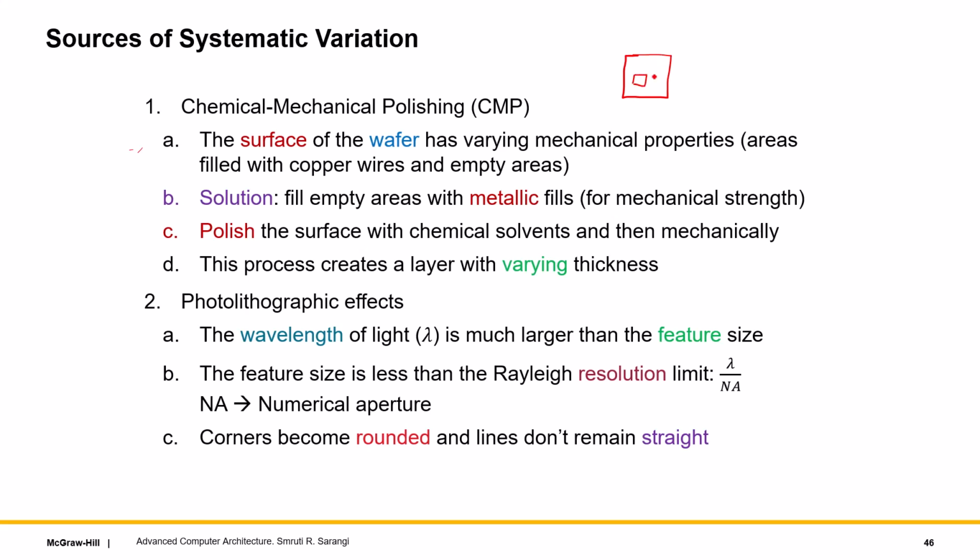So what happens is that in subsequent processing, these empty areas are soft. They are not filled with metal. So these empty areas can sort of get squished. So there is a need to look at each of these areas and bolster them, increase their structural strength. To increase their structural strength, what is done is, if this is an empty area, we create these cuboids of copper, cuboids of metal. Of course, they are not connected and they are not charged, but essentially these are like columns whose main job is to hold the area and give it structural strength.